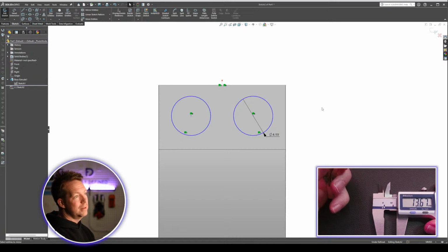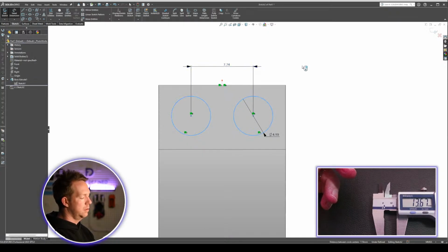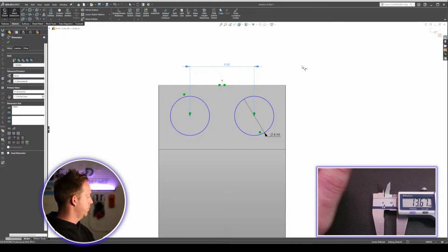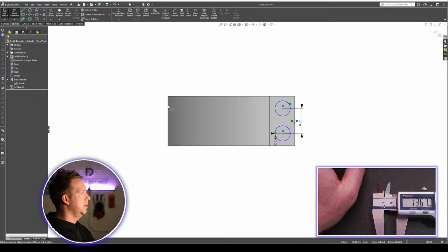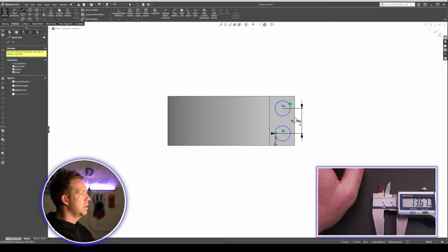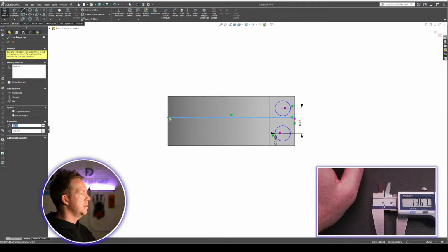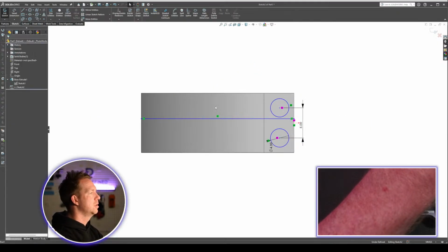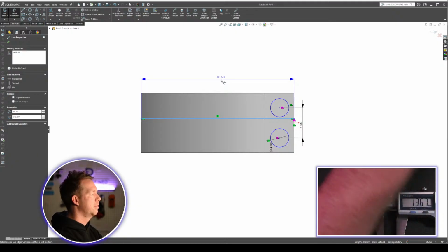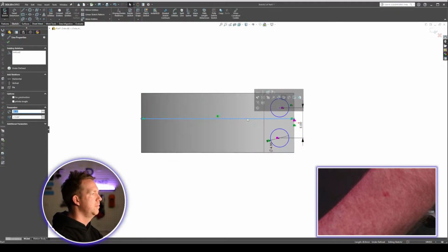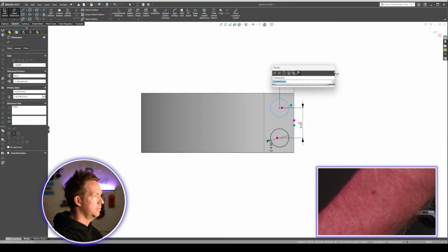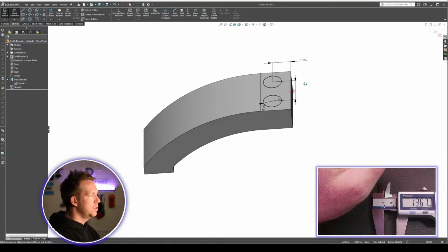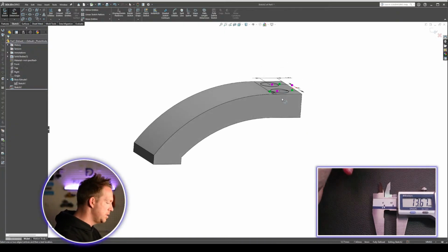Now I'm going to round it. I'm not using 7.95 or anything like that. I'm going to go to 8. It's going to be 8. Later, we'll work out the exact position that this should be relative to its length. It should be something like 4.9 from the edge. I think that overall length might be a bit wrong. It's okay. Let's put in 4.9. We just want it fully defined. We can always update the dimensions.